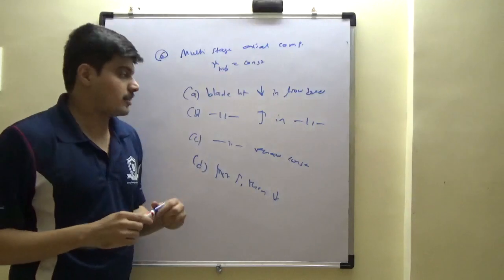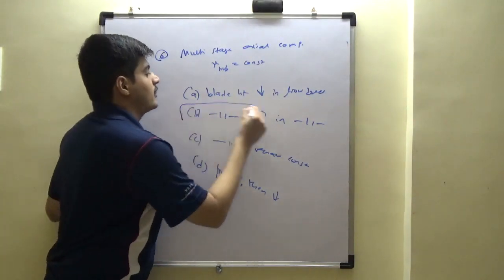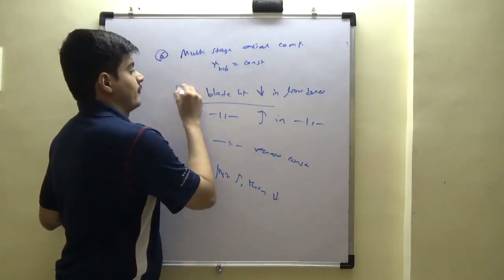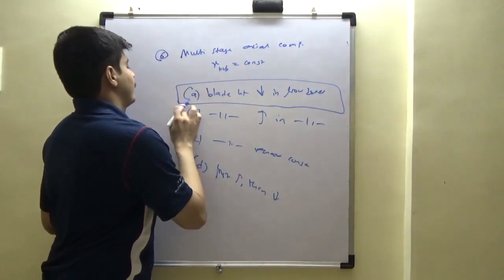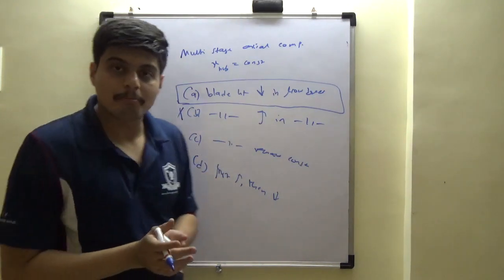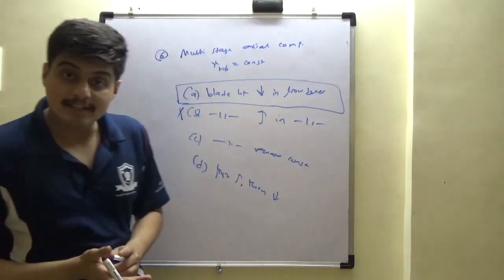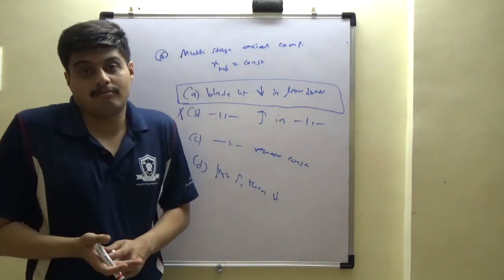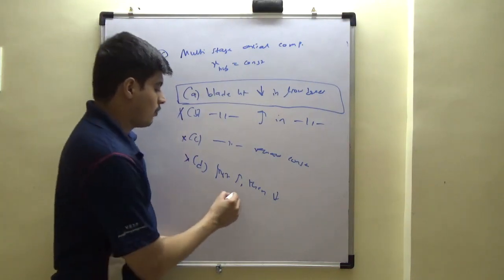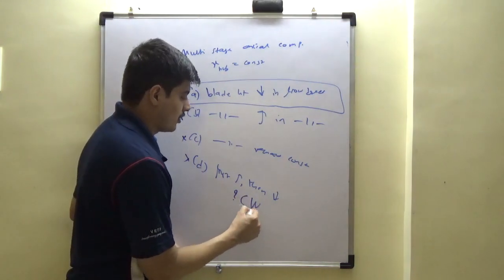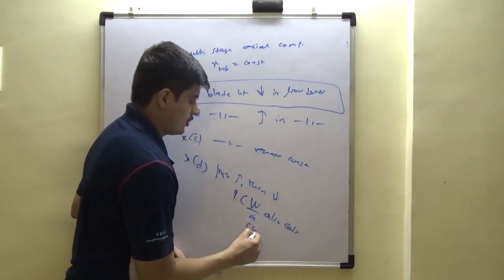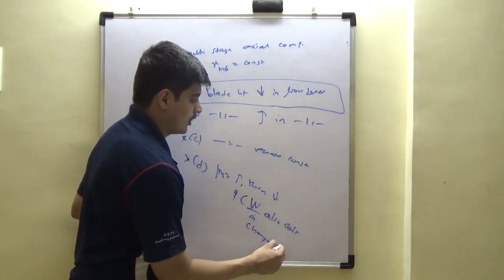Now the hub is constant. Only blade height can change, and it has to keep decreasing. If you keep increasing, more work will be imparted. More work means more density. More density means more mass flow. This is abrupt. Why? W by m dot cannot change sign.